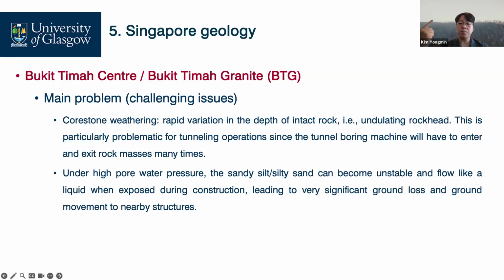Plus, under high pore pressures due to heavy rain and water infiltration, the groundwater table rises, and the sandy material can easily become unstable and flow like a liquid when exposed during constructions. These characteristics sometimes lead to soil loss and ground settlement, in turn causing structural damage and ground subsidence like a sinkhole.